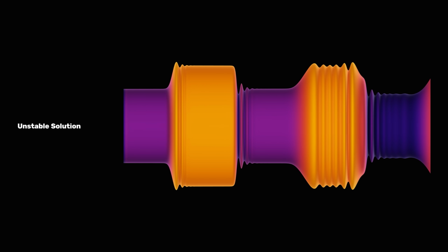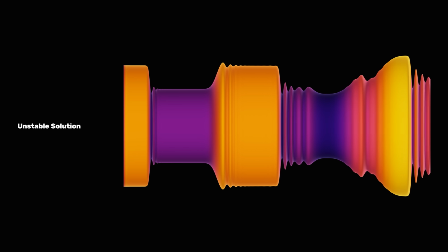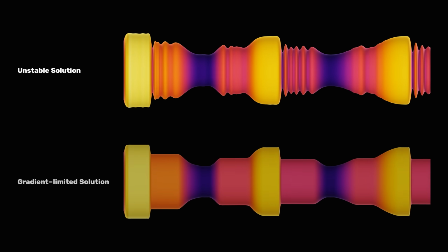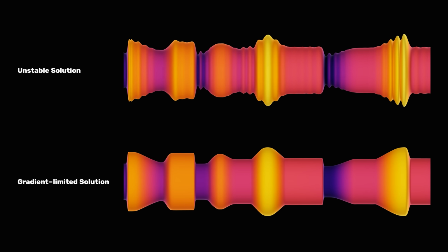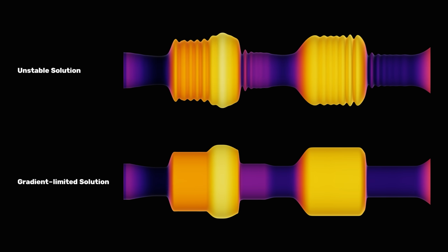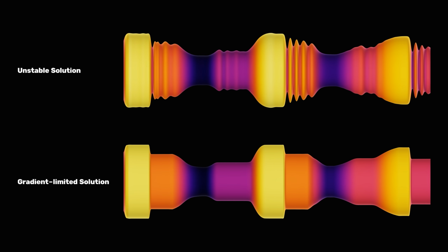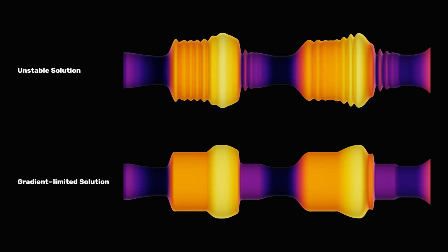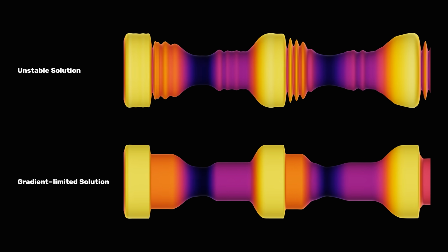The real problem is that the oscillations grow and eventually cause numerical instability, which then spreads to the rest of the simulation. These oscillations are unavoidable, and this can be proven mathematically. However, we can circumvent this issue using flux or gradient limiters. A gradient limiter is a mathematical device that pre-processes the simulation input to filter out large discontinuities, though this is somewhat of an oversimplification, as it can also exaggerate certain features.